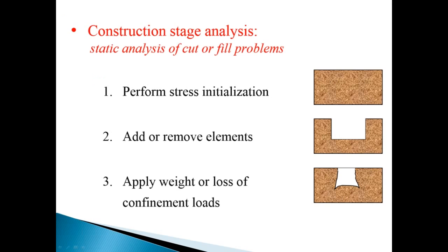And then construction stage analysis, which is especially useful, for example, for excavation type problems or projects, where you can have one model file, and over the course of that model file, you have several stages that better simulate how your excavation or how your project is done over time. So, for example, you can model temporary structures, you can do staged excavation.